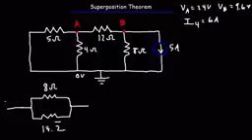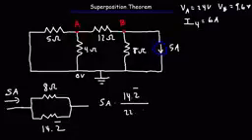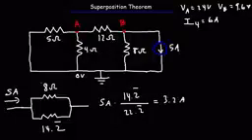And we have a current of 5 amps flowing through this current divider. To calculate the current flowing through the 8 ohm resistor, it's going to be 5 amps times the other resistor divided by the sum of the two, which is 8 plus 14.2 repeating, that's 22.2 repeating. So this will give us a current of 3.2 amps.